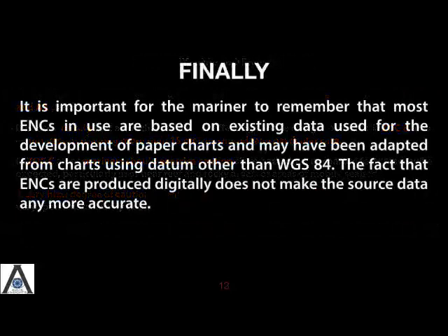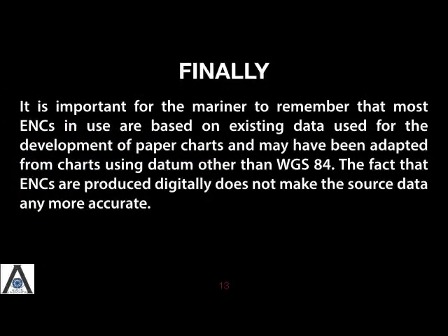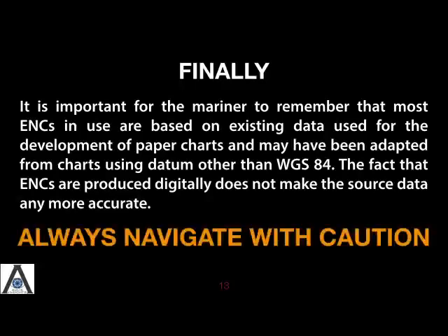And finally, it is important for the mariner to remember that most ENCs in use are based on existing data used for the development of paper charts, and may have been adapted from charts using datums other than WGS 84. The fact that ENCs are produced digitally does not make the source data any more accurate. Always navigate with caution.